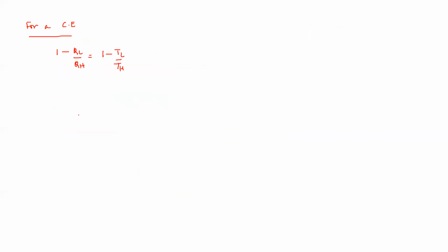And for any general engine, 1 minus QL by QH, which is my efficiency, would be less than 1 minus TL by TH. Keep this in mind.